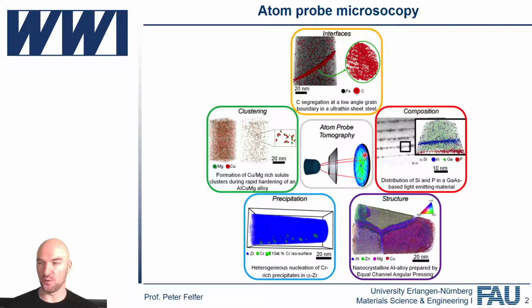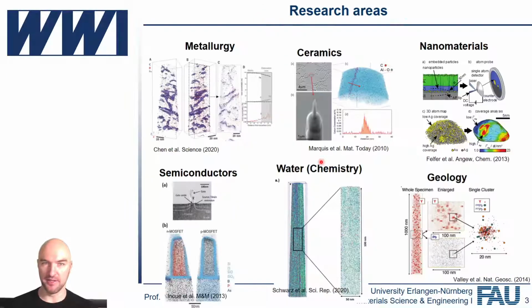And so we can think of the atom probe experiment as a layer by layer tomography, slice and view, if you will, each slice just being one atom, slice and view on a sort of curved surface. And this gives us the ability to create a 3D reconstruction. And this is where the tomography part comes from. And we can do that on a variety of different materials.